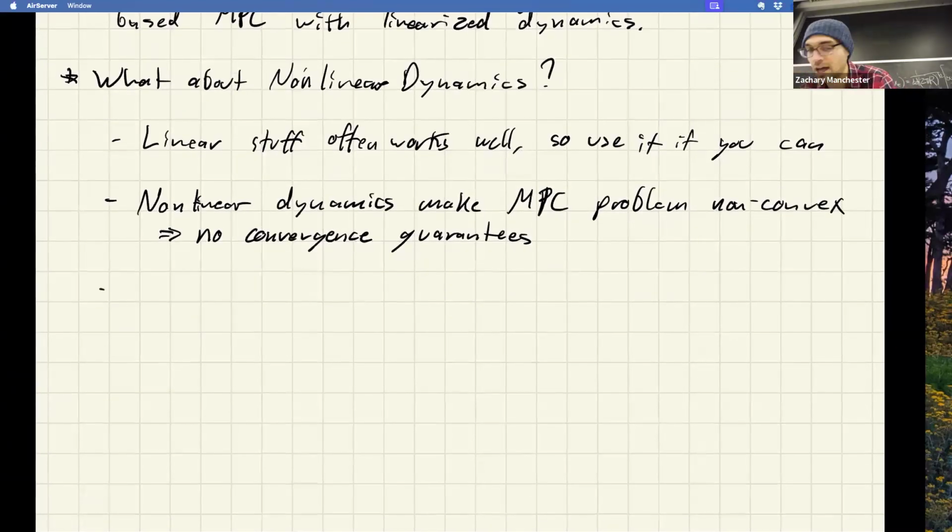But that said, lots of people do this and it works really well in practice if you can hand engineer some stuff, do a bunch of tuning, Monte Carlo it a lot. You can get this to work extremely well. Nonlinear MPC is basically what Boston Dynamics does on Atlas. So all that insane stuff that you see them do, that's nonlinear MPC, where they're basically doing this stuff online. They're the best people in the world at it, and they've really dialed that stuff in, and they've done amazing stuff there with years of effort. So you can get it to work, right? But it's sort of the Wild West, and it takes a lot more tuning and effort to make it work than the convex stuff.